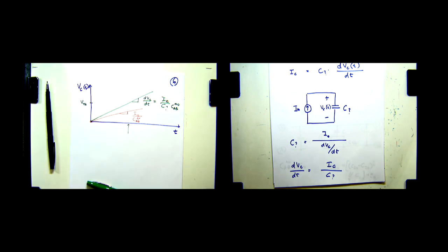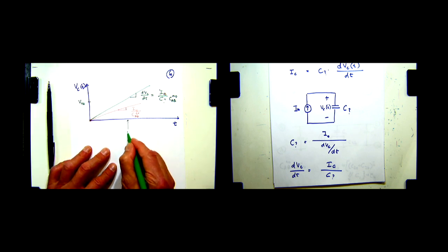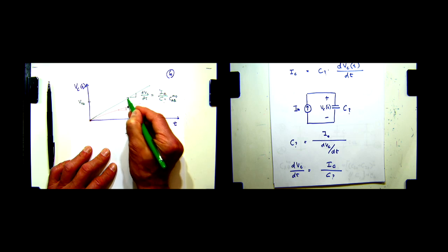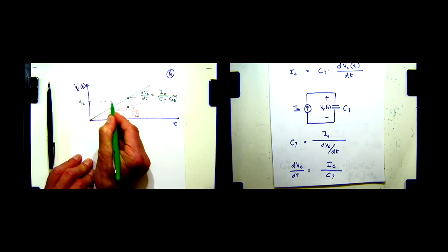Well, if we wait for long enough, then with or without finger, we're going to get to this voltage. In fact, if we wait long enough, what voltage are we going to get? Infinite, right? It just keeps rising. So we'll have to deal with that also. Otherwise, we're going to zap the people using our touch screen or something. That would not be good. Okay, so we probably have to always measure at some time T1 or so. And then we have to determine is the voltage above or below that threshold, right?